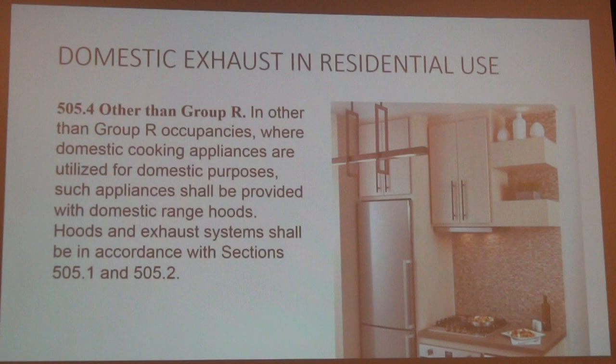You can get that in, even in residences still. They'll put the stove in the corner, which is stupid to begin with. And now you've got the burners that, in the manufacturer's instructions, they want that burner to be 6 inches away from a combustible wall. You got that with some of these fancy wood hoods, where they're not high enough and they encroach in that space. You're right.